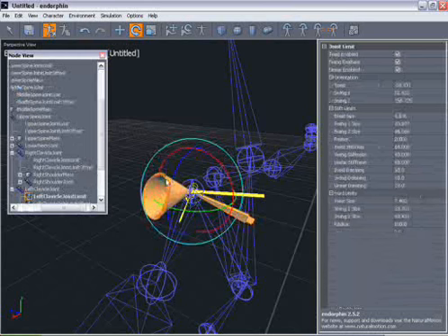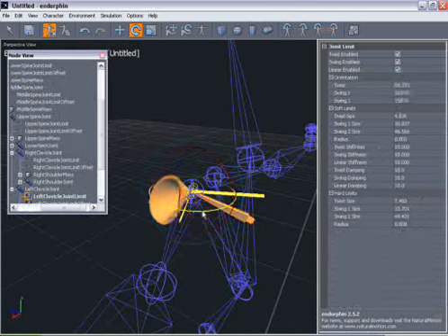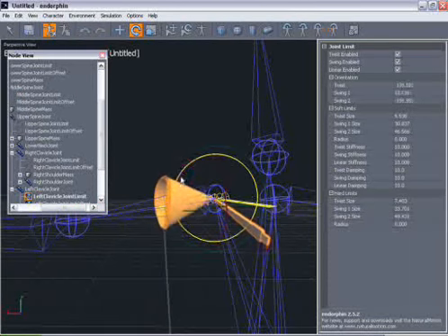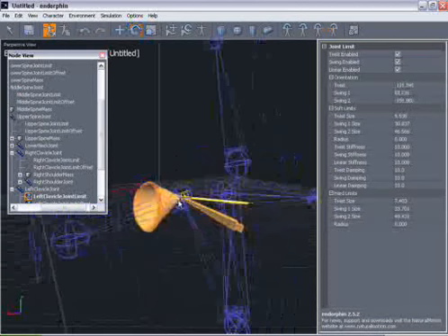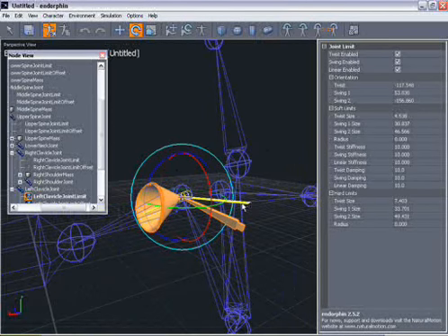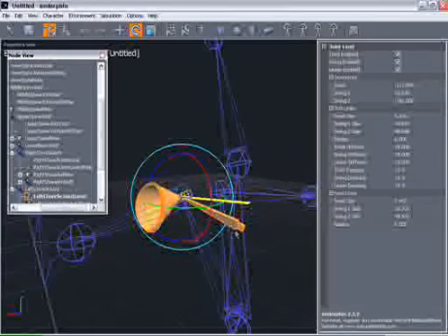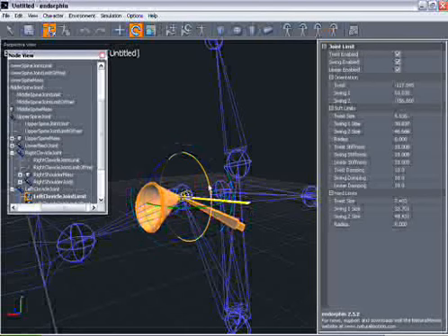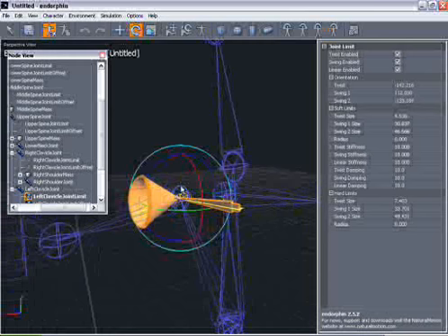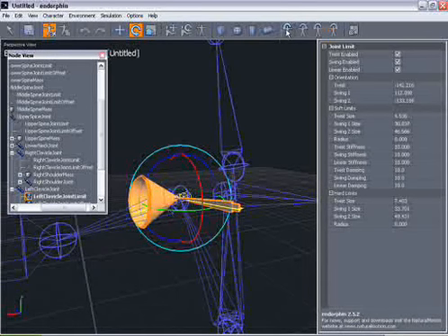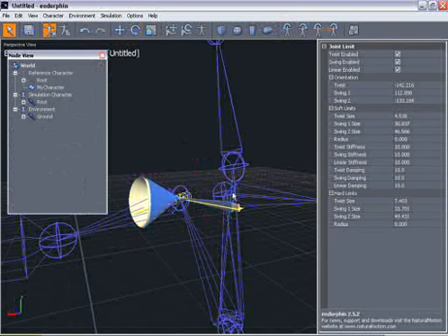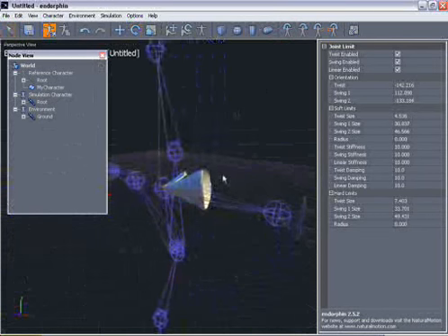So to rectify that, we can select it and then just easily rotate it back into place. And I'm going to move that down a little bit as well. Now you can also see that the twist limit, that's outside of the resting place for that limit as well. So we just want to rotate that up, and there we've got both of them sitting in the same place. And again we can just mirror that to the other side, so we've got the joint for the other side behaving exactly the same.